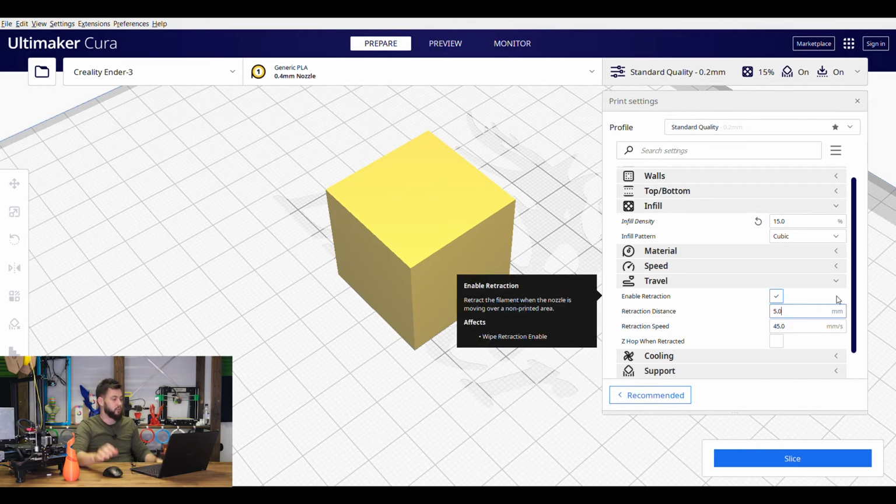So this also helps a lot. What this will do is, if you're printing, your filament will jump. Your hot end will actually jump up and retract at the same time, and then it will move and come back down again and then re-extrude. So it jumps up before it moves instead of just moving across. That jump up sometimes is enough to actually sever that excess filament that's there. So when it starts printing again, you've got no more stringing.